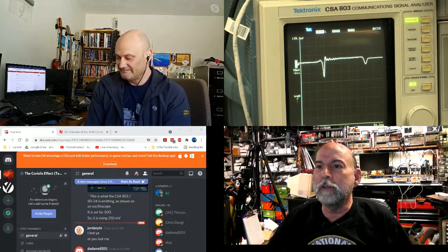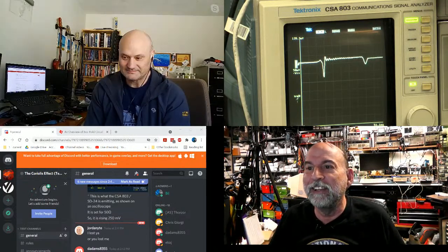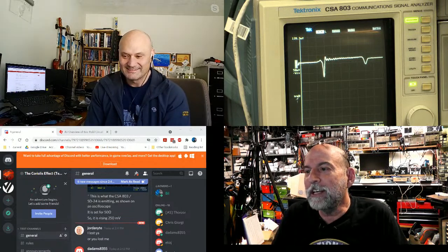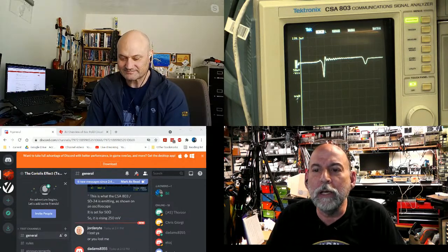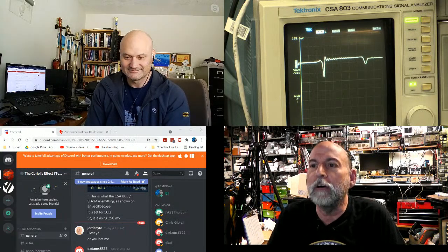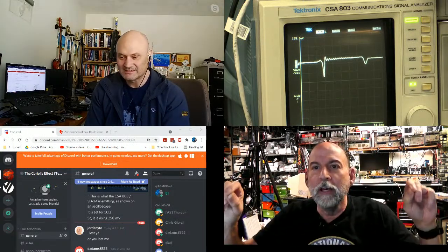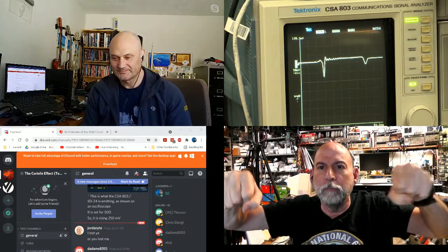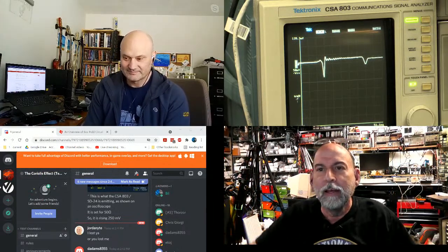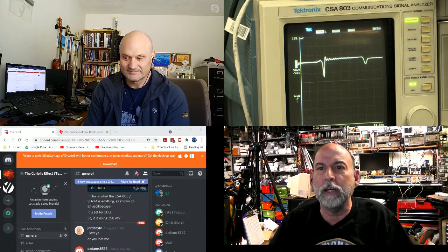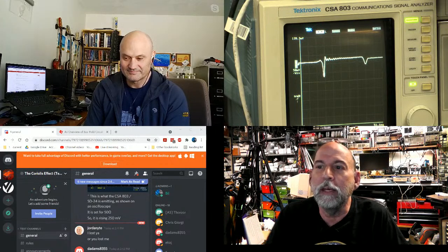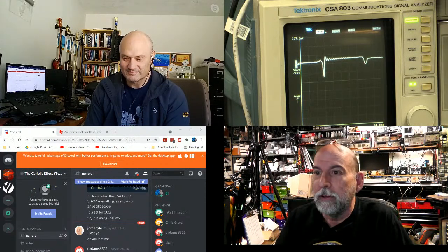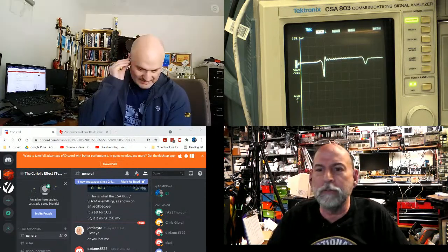Or the board doesn't crystallize from the heat. So one technique, we used it in the old days, was board stiffeners that also doubled as power rails. So you would have a board with slots in it, mount this bus bar to the board, and it would hold the board rigid. My stuff was small time stuff, but I could easily see somebody dumping 20 amps through one of those and not think anything of it. Yeah, I'll have to find a bus board.